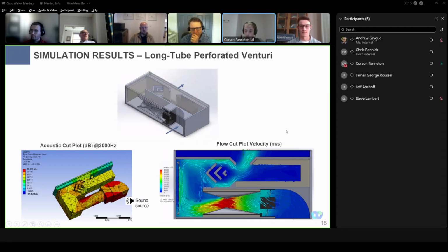To improve the calculation speed and simplify the meshing on the flow sim, in our first simulation we decided to opt out of the perforations. We made a preliminary assumption that the small perforations would have less effect on flow and more effect on acoustic performance. In this one we made sure to include the perforations in full detail, but we didn't do that here.